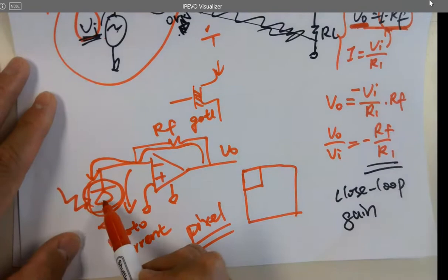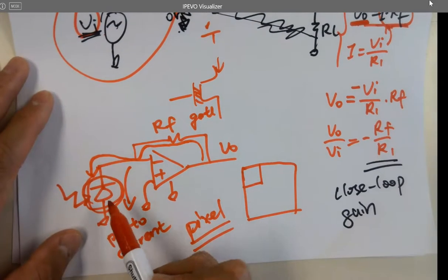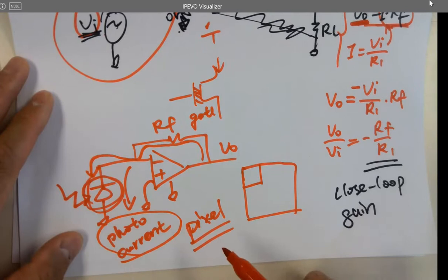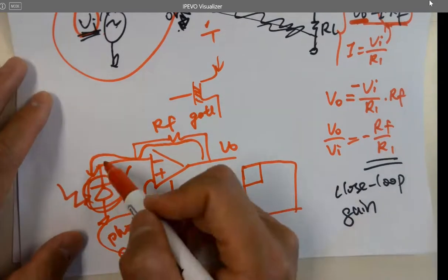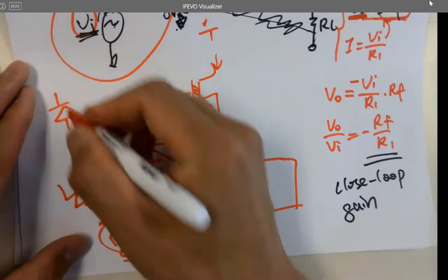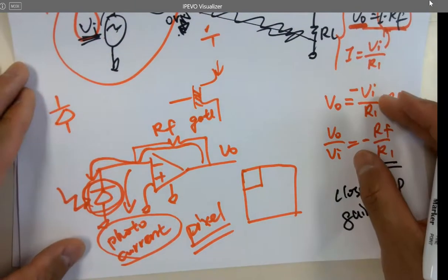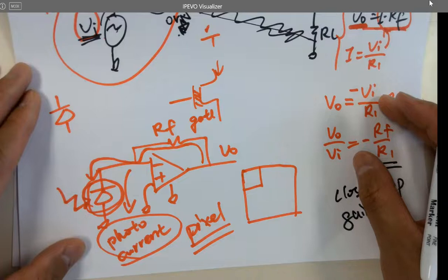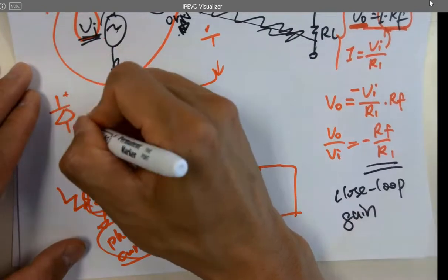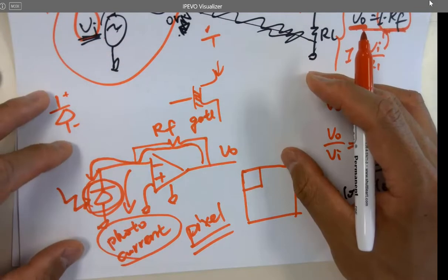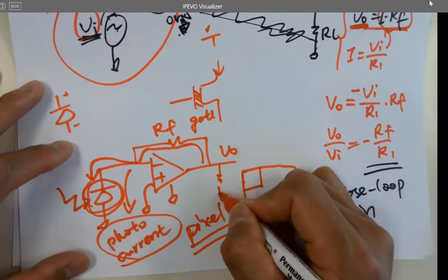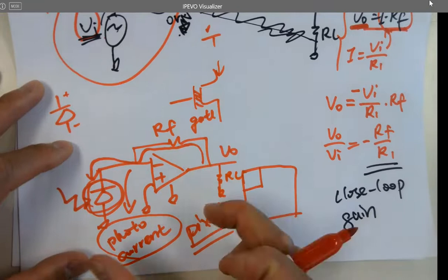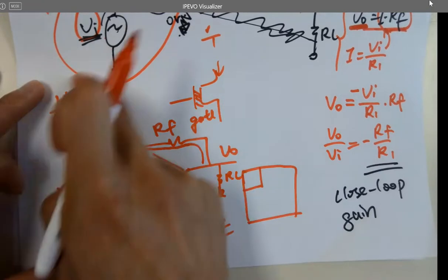Whenever it receives the light or photons, it generates photocurrent. And where's the current from? If you disconnect the photodiode, just grab a photodiode, nothing's going to flow. It probably will generate some charges over here, but nothing's going to flow, right? Only when you have a circuit, there's a load, you form a circuit so the current charges can flow freely in the circuit.